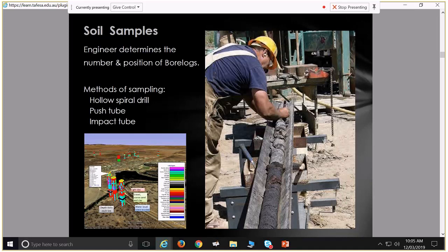But for inaccessible areas, I've seen a soil sample done inside a hallway of a house, taking up all the floorboards in the hallway, of course, setting up a tripod, and then using a two-stroke motor with a rammer to ram that steel tube down into the ground.